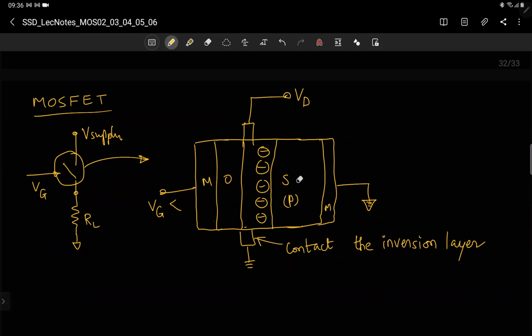And this Vd is connected to P only by depletion, which doesn't allow easy charge flow. So this Vd and this contact at 0 are isolated without any carriers. So there will not be any current flow because there are no carriers to move.